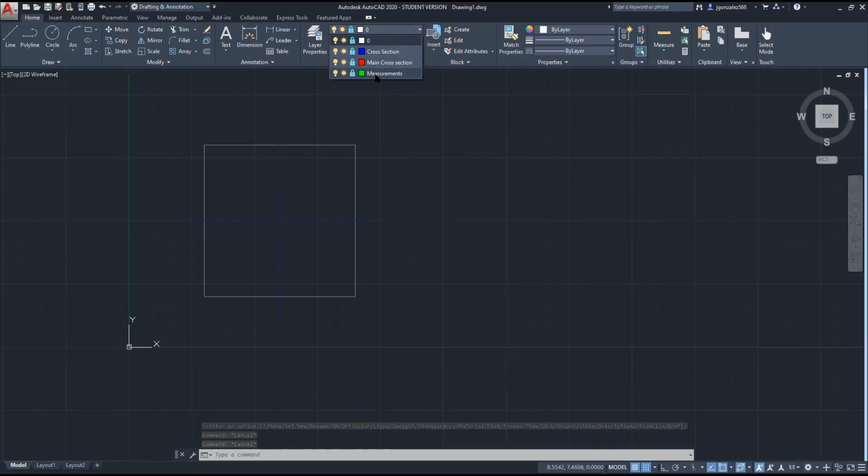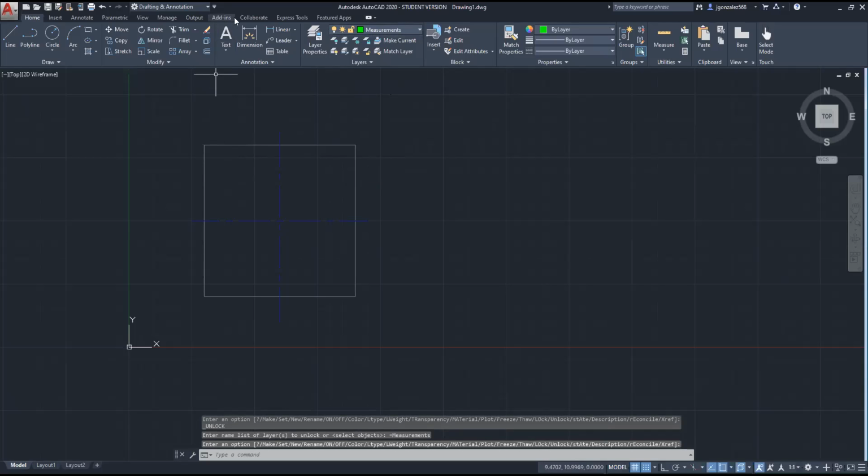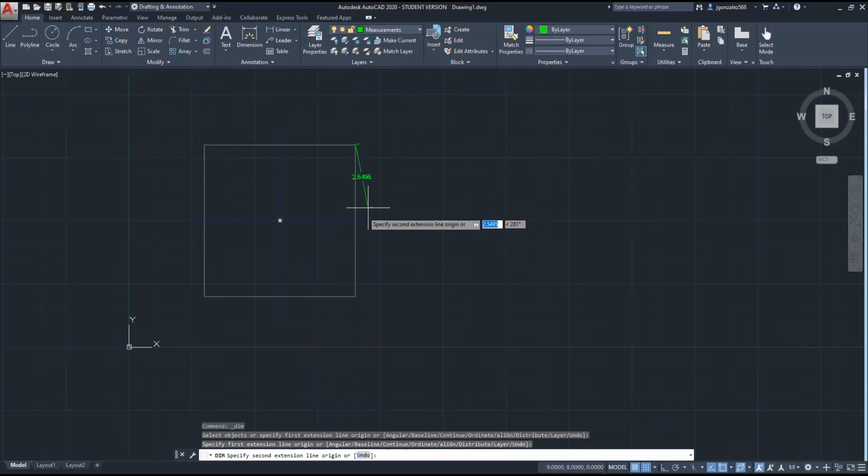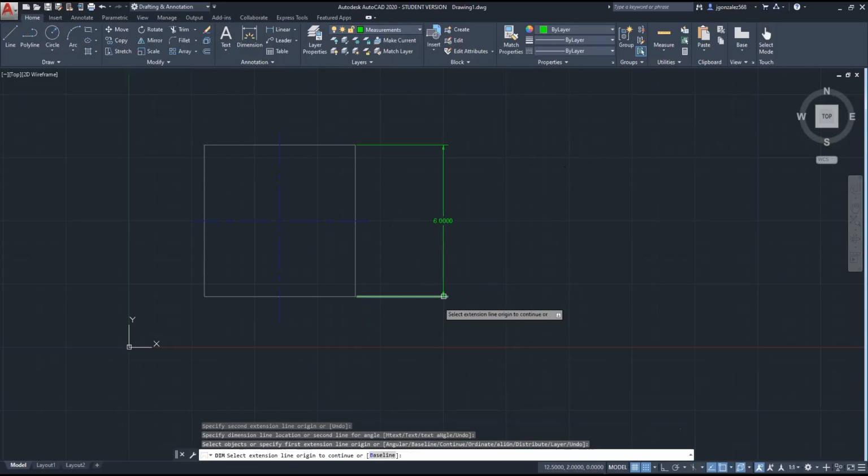Let's do the measurements. So switch to measurements and unlock. I'm going to measure my box that I just made. So click dimensions. Once you click the dimension tool, click a corner and go all the way down and measure that side. Since it's a 6 by 6 box, it should give me a dimension of 6. Now, how many decimal points depends on the precision, which I showed you last time. Although there is a separate menu for customizing the measurements, but we'll talk about that more later.